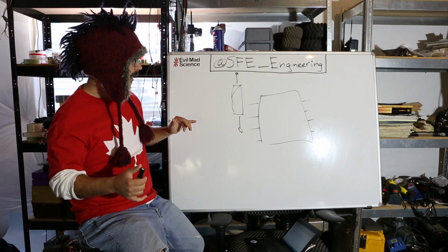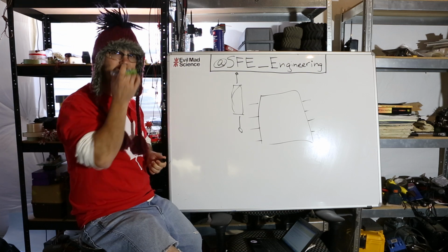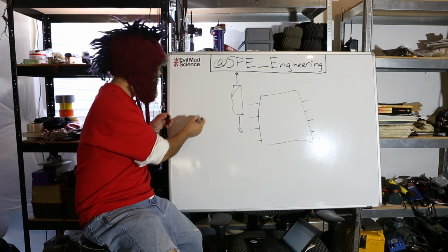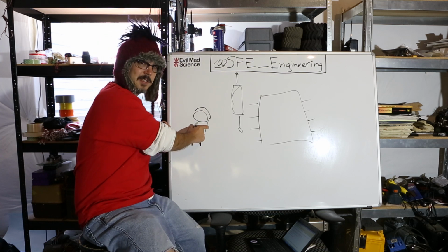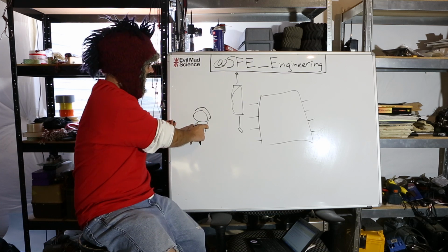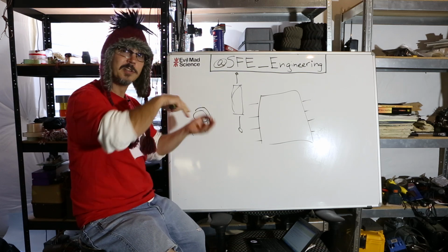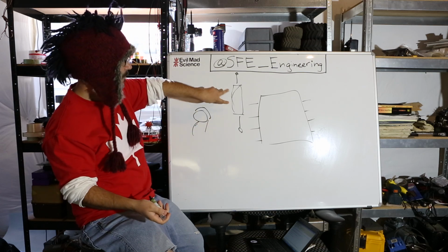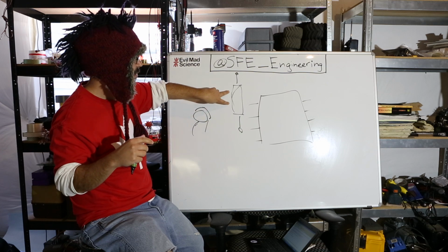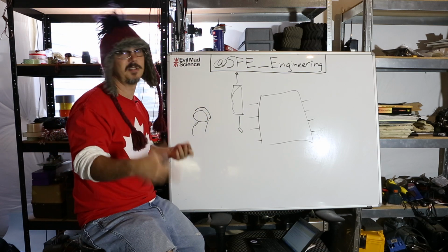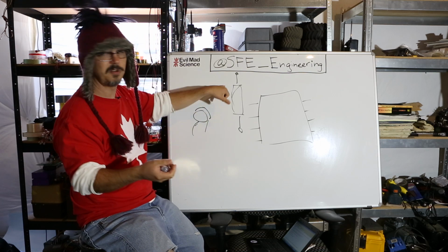Now, in terms of component types, if you're using through holes, caps have gotten pretty good about tightening up, right? Because it's only a couple of plates on a pin. And these are usually spaced 0.1 inch apart, or in some cases even tighter. So that's not that bad, right? That's almost an 0603, 0805 package width. You can deal with that. Resistors are the same thing. The components have gotten smaller. It used to be that quarter watt resistors were the norm. Now you can get 6th watt or 8th watt. They're really tight.